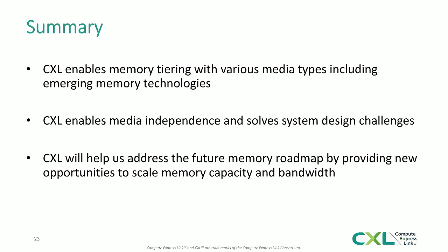So in summary, CXL allows us to build various memory tiering solutions with a variety of media types, including the different emerging technologies. And it allows us to do so in a media-independent fashion while addressing some of the scaling challenges, both from the media side as well as from the system side. And finally, it allows us to build a future memory roadmap here by providing us with new opportunities and new potential architectures so that we can continue to scale the memory capacity and bandwidth in the most efficient fashion for our future server generations.